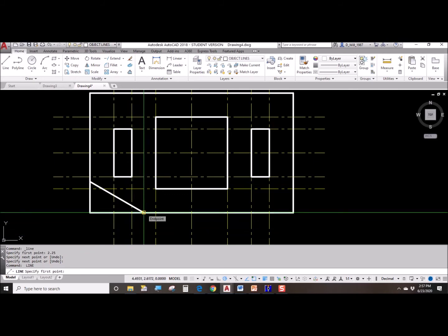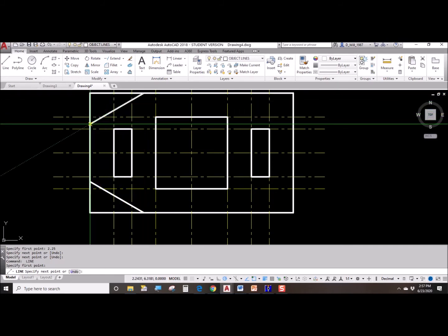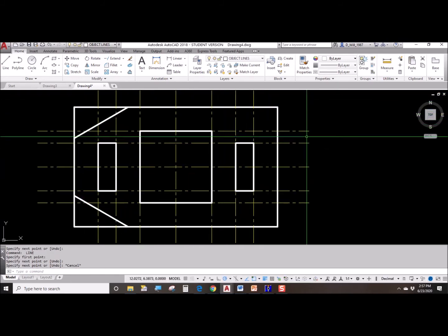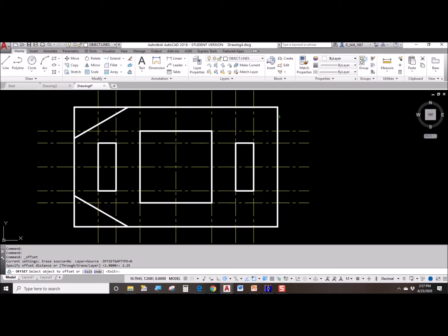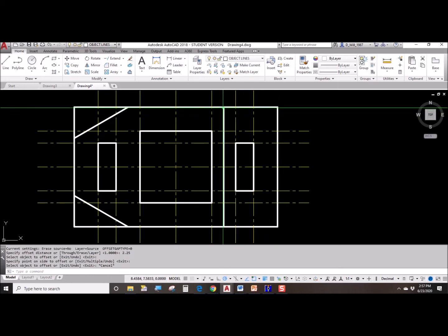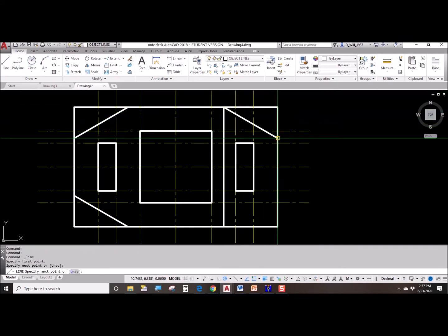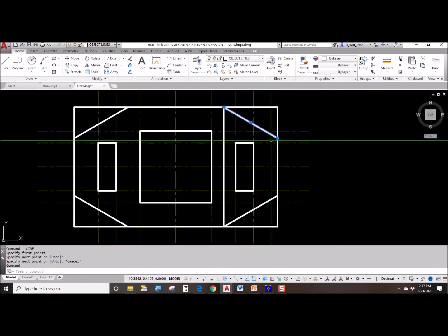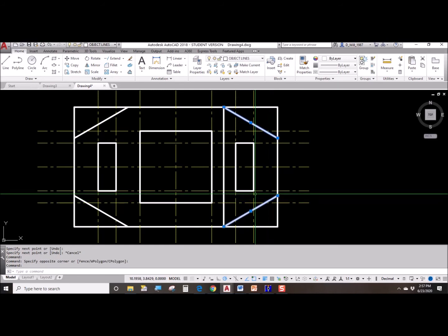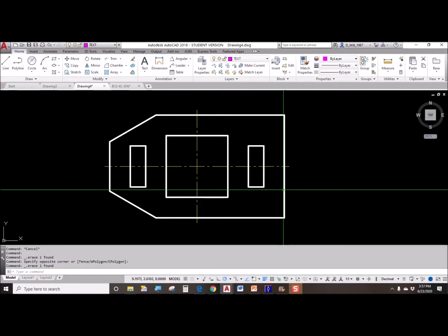I can go and track that point up to here and then go down at 30 degrees. That's nice. If you wanted to, you could also offset 2 1/4, 2.25. Right, and that tells you where to begin your 30-degree line going down. Bam. And bam. Now, of course, both ways work. Both ways are awesome. Another option would be to use the chamfer tool.